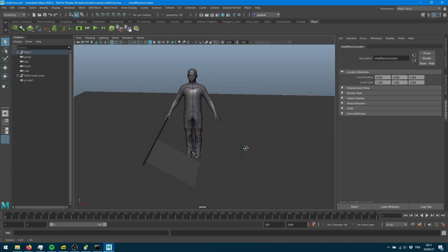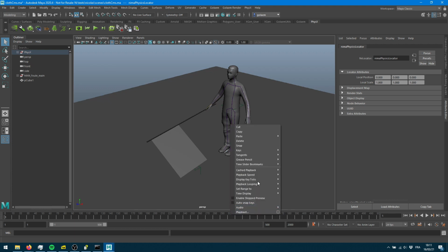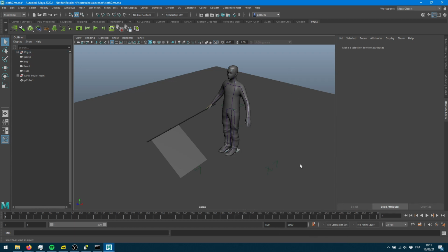The first thing you really want to make sure of when you're dealing with cloth simulation is that your playback speed is set up to play every frame. Similar to Golaem, cloth also relies on simulation, so it means that every single frame needs to be evaluated. If you're using real time, Maya will optimize and probably skip some frames when the computation is heavier. So make sure to use either play every frame free or play every frame max real time, which will cap your display frequency to 24 or 25 FPS depending on what you provided. This is the first thing you need to make sure of.